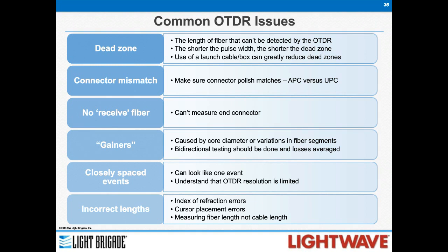If you see a break in your fiber and it's 12,252 meters away from where you're standing, you're going to have to adjust the fiber length for the cable length, and it won't be quite that far away in the cable because there's more fiber than there is cable. So those are things that technicians should know about. A lot of the manufacturers of the test equipment can help you with those calculations. We can certainly help you with those calculations, but don't mistake fiber and cable length for being identical.